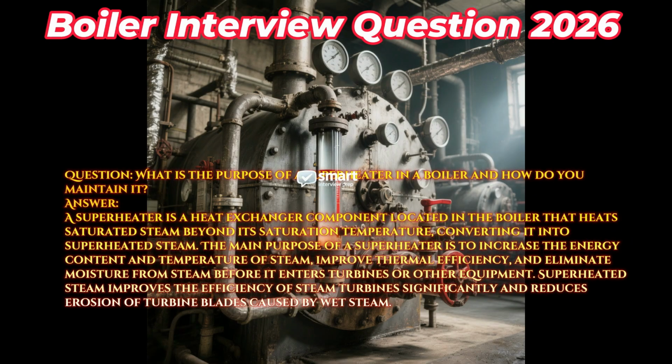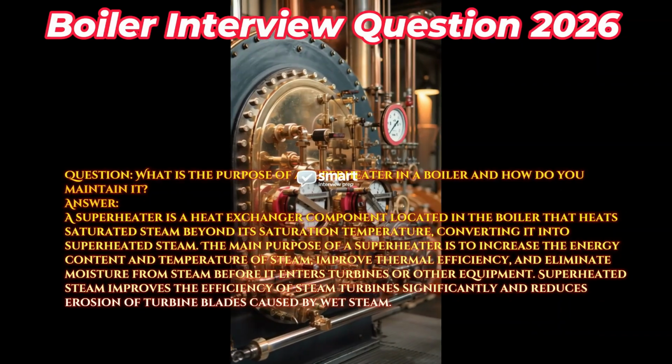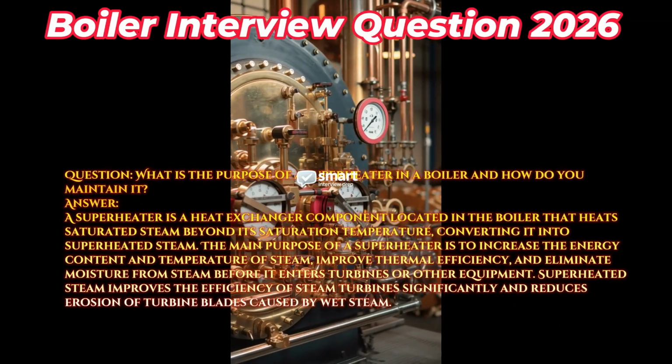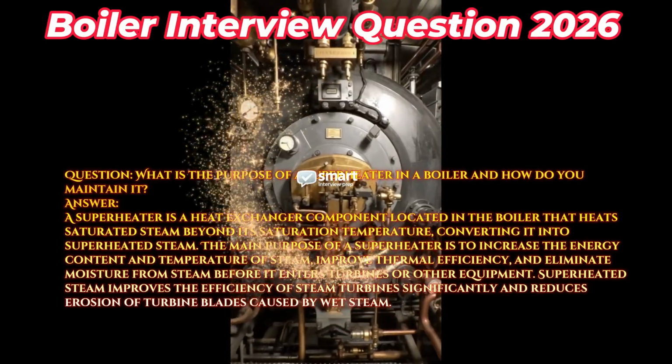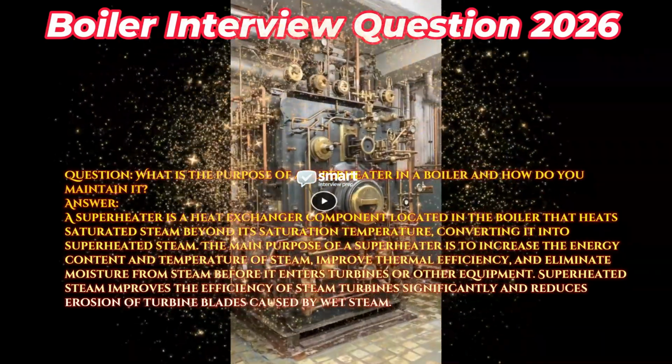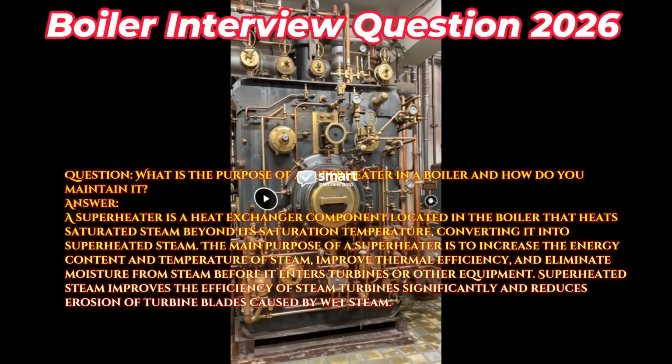The main purpose of a superheater is to increase the energy content and temperature of steam, improve thermal efficiency, and eliminate moisture from steam before it enters turbines or other equipment. Superheated steam improves the efficiency of steam turbines significantly and reduces erosion of turbine blades caused by wet steam.